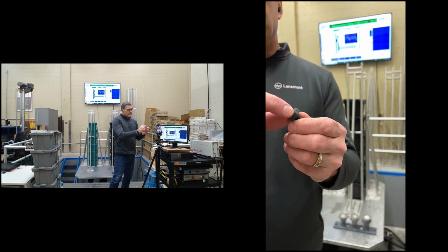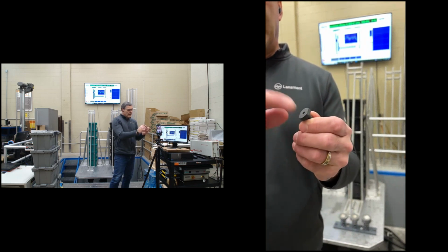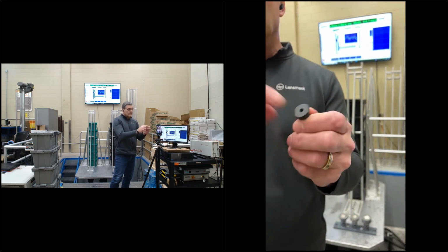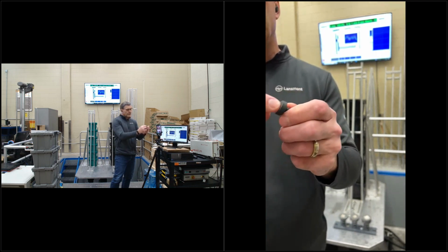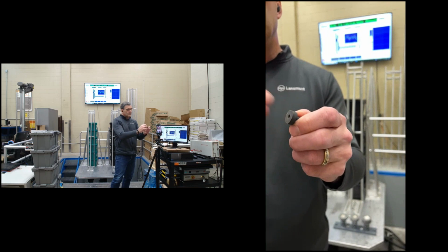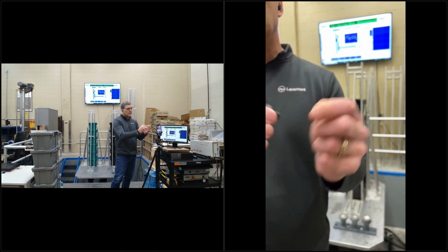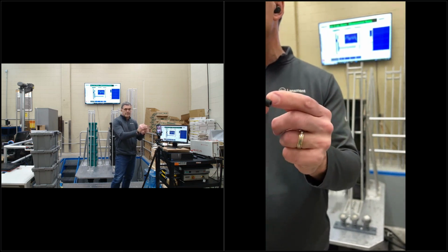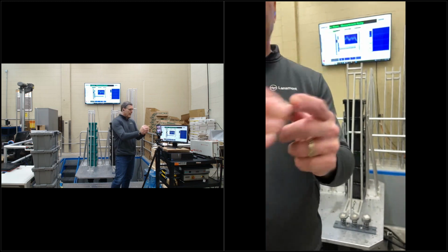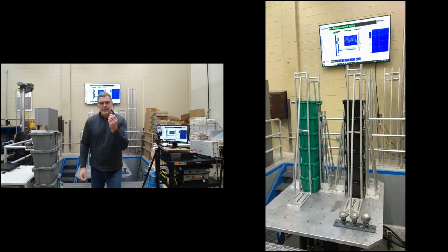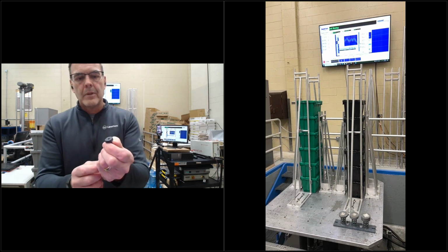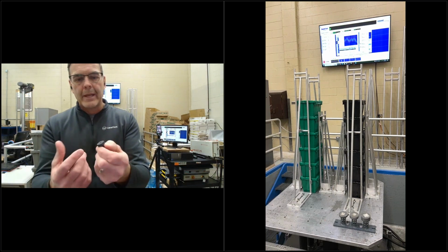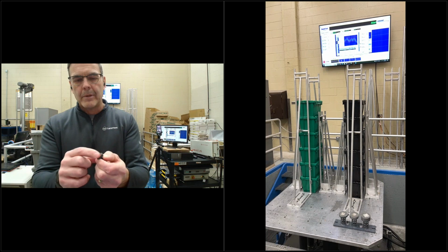A lot of the accelerometer manufacturers make smaller studs without this piece here, but just the threaded insert here. So you can attach your accelerometer to this, and then you can glue this to this piece. I'm backwards in my viewing, but, oh, this is easier. So you can glue these pieces to the product, to packaging, without having to mess up the accelerometer itself.